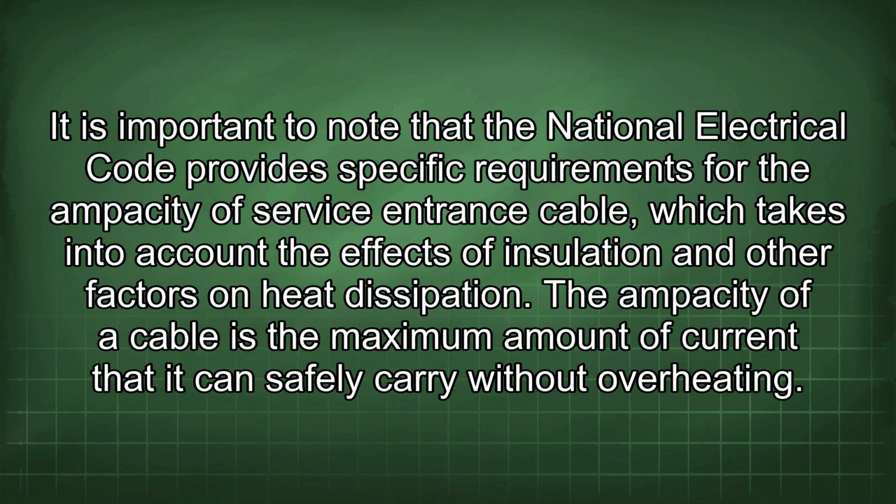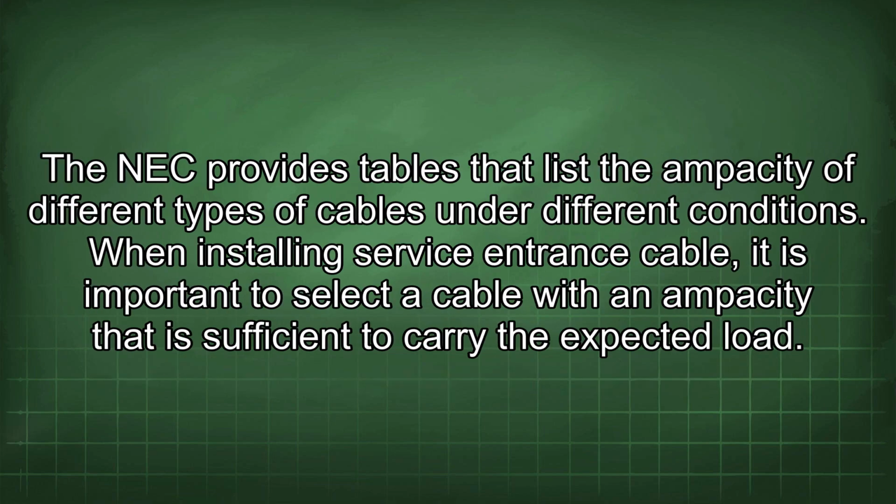The ampacity of a cable is the maximum amount of current that it can safely carry without overheating. The NEC provides tables that list the ampacity of different types of cables under different conditions. When installing service entrance cable, it is important to select a cable with an ampacity that is sufficient to carry the expected load.